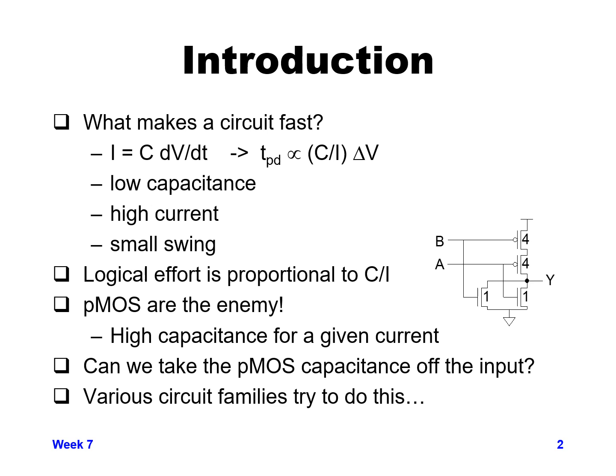So before we go into some of the new logic types that I'm going to talk about, let's do a little refresher on what makes a circuit faster than a different circuit. Just as a starter, if we have capacitance in a circuit and we want to change it from low voltage to high voltage, from ground to VDD, keep in mind the equation: current through the capacitance I equals the capacitance value C times change in voltage over change in time, or C dV/dt.